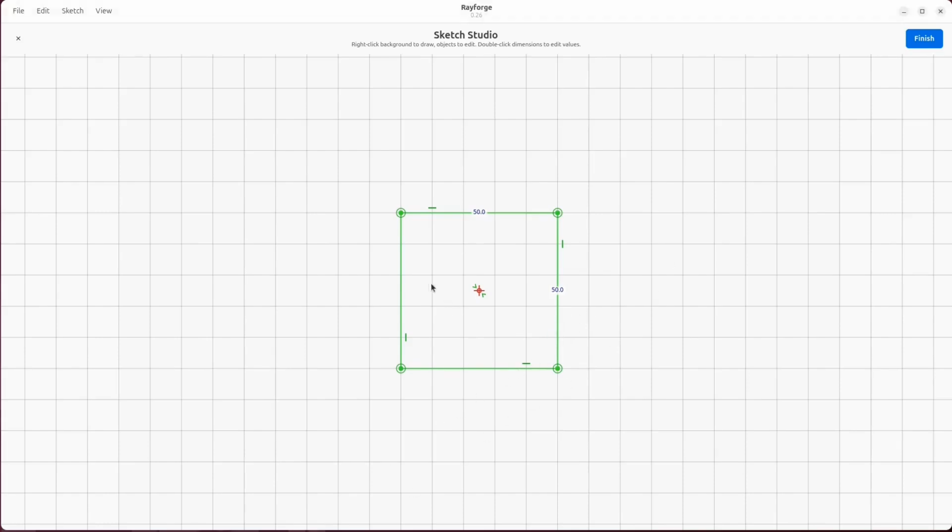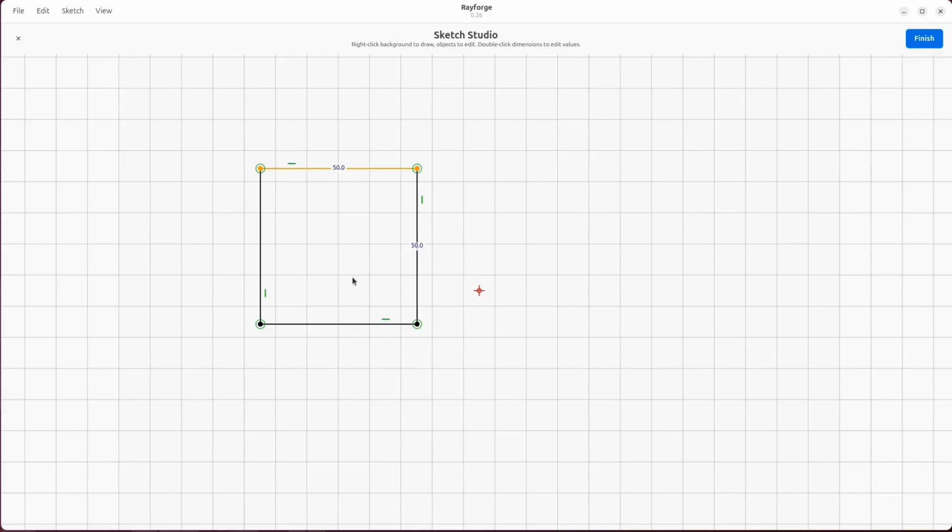Now next, there's also the concept of construction lines. So let's remove this symmetry for now, because I want to move this around. Let's say this is here, for example, and now I want to place something here in the center. I want to place a circle in the center. First I press G followed by C to create a circle. And then I press G followed by L to create a line from here to here. And then I do that again, GL.